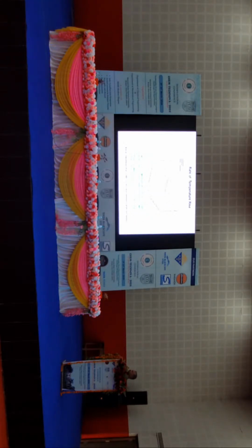Next one please. So rate of temperature rise: obviously you can get the slope of the temperature versus time plot, right? I have shown it in the initial stage. So I have taken the derivative of each plot, and that is referred to as the rate of temperature rise. This is also one important parameter you should know when you study the curing of resin.